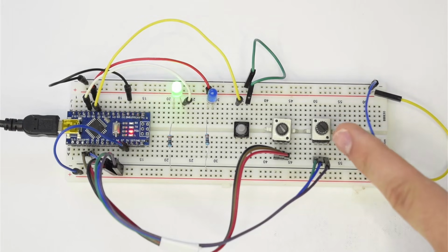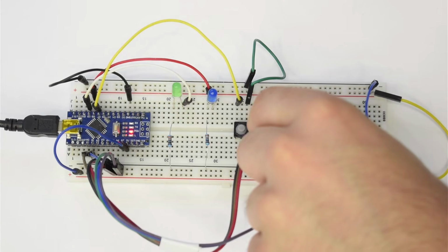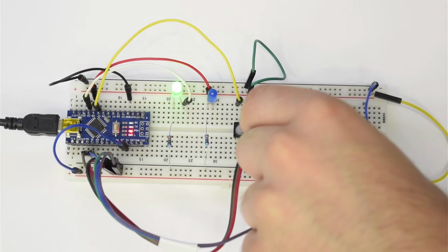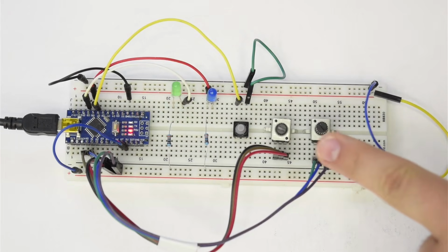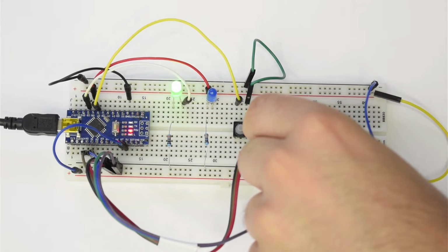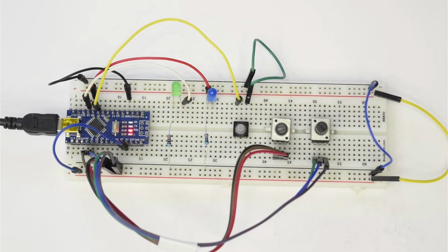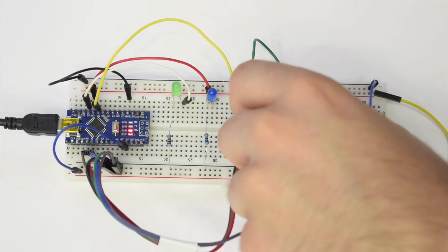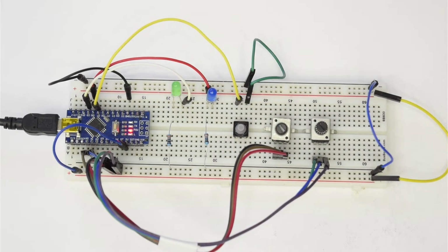Now, we know that this first potentiometer varies the blink duration. You see how, as I'm turning this potentiometer, the LED blinks more and more often. If I turn it this way, you see it blinks more rapidly. And when I turn it all the way clockwise, it turns on for 1 second and off for 1 second. I also changed the code to blink every second instead of every 5 seconds. That is a modification I made. I'll show you that later.